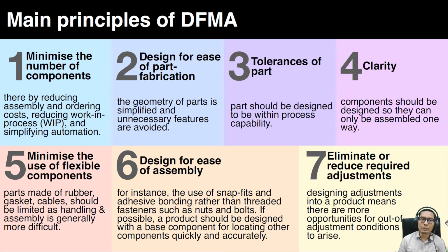The second principle is design for ease of part fabrication. So the geometry of parts that has been designed is simplified and unnecessary features are avoided. The third principle is the tolerances of the part. The part should be designed to be within the process capability. So when we design the part, we should be able to define the process capability and match it with the tolerances of the part that we design.